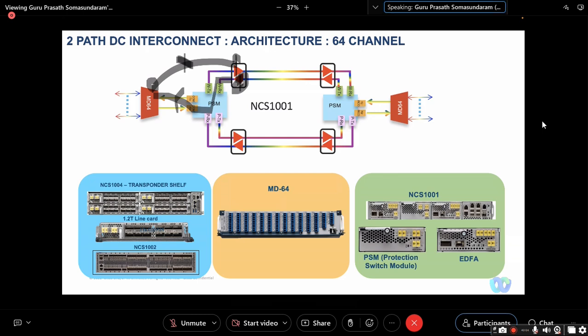Okay, this scenario is where the fiber from the mux to the amplifier is totally cut. But if this is degraded, meaning there is loss in this fiber? No, degraded doesn't matter. As long as the COM-TX port receives power, it can be in the minus 20 dB range, it is fine. It'll work. When it goes below minus 40, that is when this amplifier will shut off.